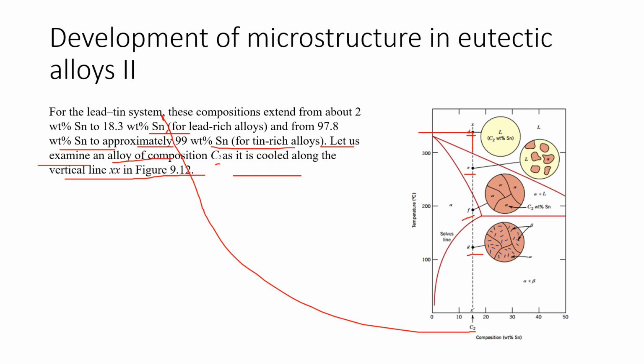But as the boundary of the liquidus line is crossed, the changes that occur are similar to the previous case, as we pass through the corresponding phase regions, as demonstrated by the points D, E, F. These points are just above the solvus intersection. The solvus line is this one, the downward one, and just above the solvus intersection is point F.